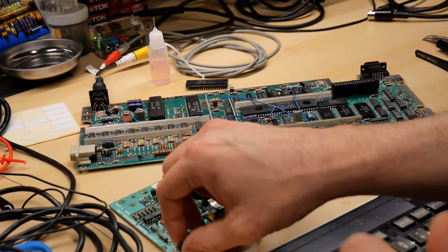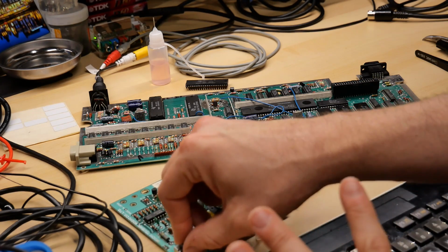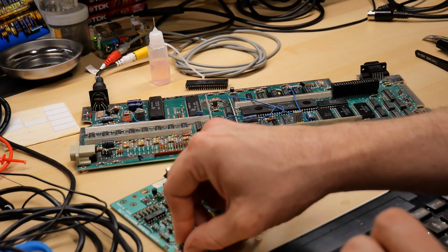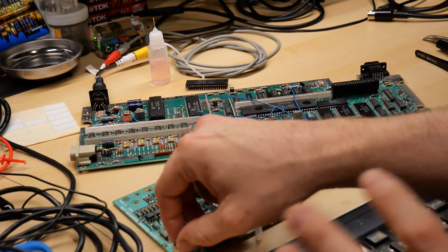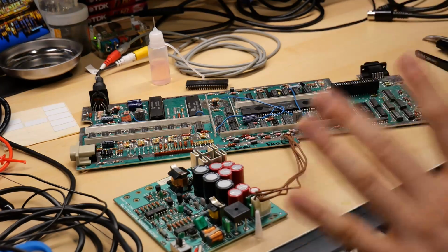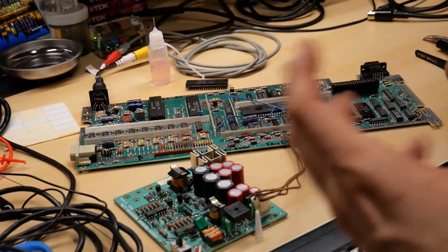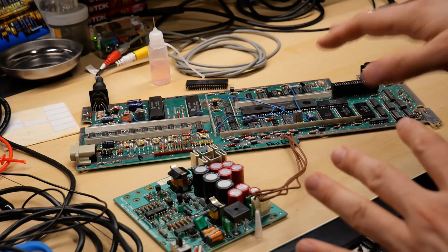There we go, we're getting continuous tone, which implies that sound chip is powering up and working, but it's not getting initialized, so the computer's not booting at all. Let me try turning it on one more time. Yep, and it's slightly different, the tones each time. And what happens with this chip is it boots up with random data in the registers, which is what creates those random tones, and then it's the BIOS or the ROM's job to shut that off.